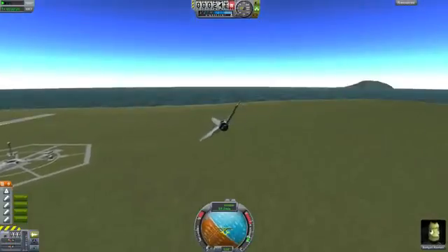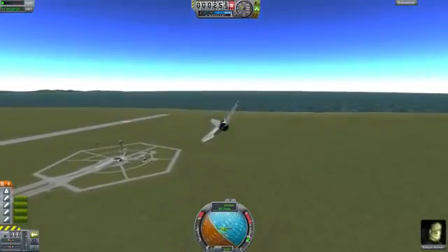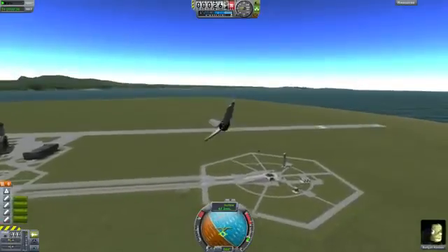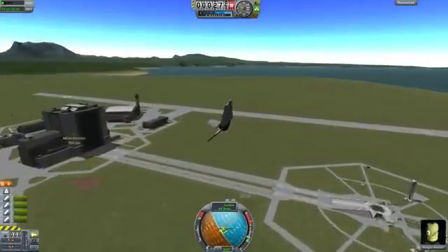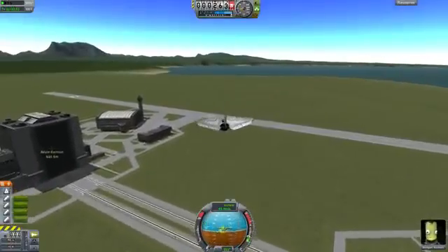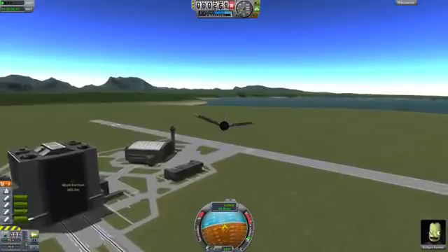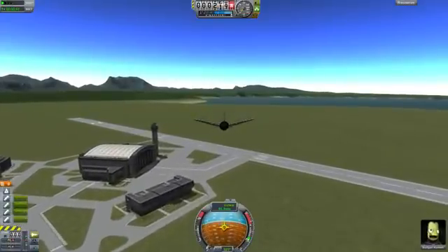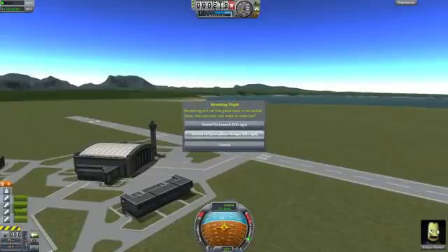And this is basically these wings that arch upwards. This is a stability enhancing feature. It makes the aircraft easier to control by basically wanting it to restore its attitude to a vertical attitude, more or less. So it becomes much easier to fly these things. Now, let's, of course, see what happens if I do it the other way.